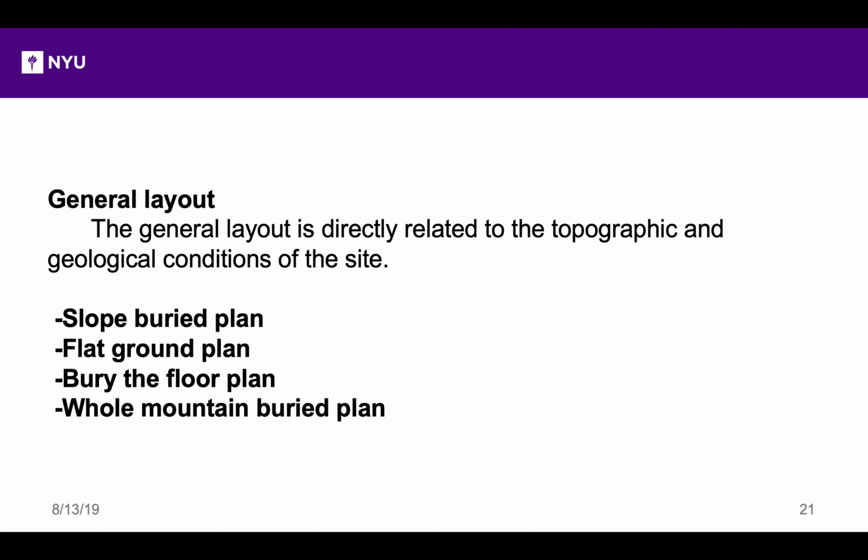Third is the underground barrier plan. The ground workshop is arranged on the upper terrain or platform of the hillside, while the underground workshop is arranged in the mountain below the platform on the vertical plane. The ground workshop is located above the underground workshop. The ground and underground workshops are mainly connected by vertical shafts. Three vertical shafts are arranged at the top of the workshop, which are respectively used as the main steam pipe, the main water supply pipe, and the personnel channel. A shaft is arranged on the roof of the fuel plant to serve as a fuel transportation channel, and a shaft is arranged in the nuclear auxiliary plant to connect with the surface.